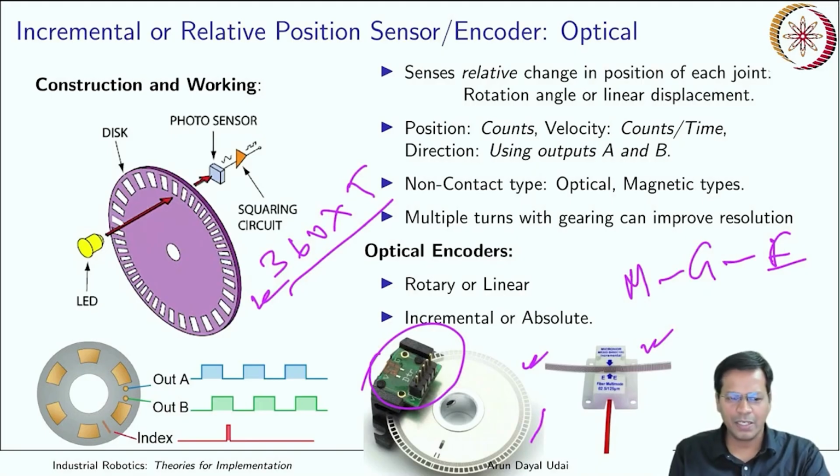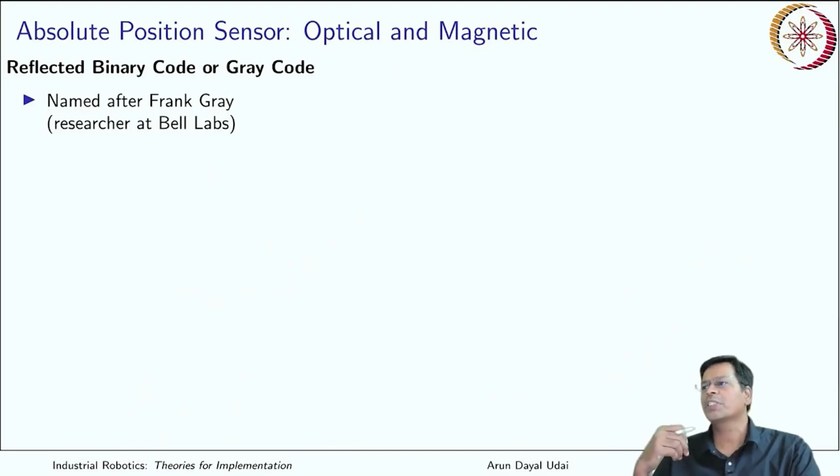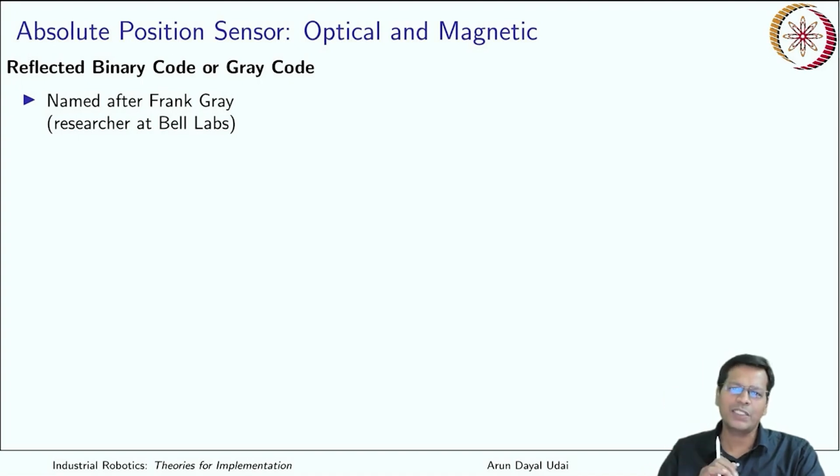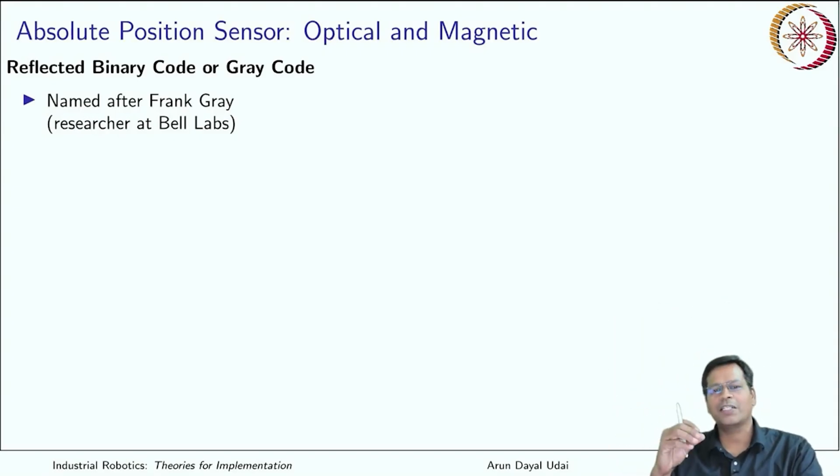Okay, so yes, this is an incremental sensor, and now you see how an absolute position sensor can be made, which can store the value, at least the starting value. So if it moves even when the system is shut down, when it starts, it can directly get where I am. Initially, if you remember your printer, whenever you start your printer, your head goes to the home position. Why? That is probably an incremental encoder. The strip which I showed you is pulled out from such a printer only. So yes, it is an incremental sensor. So your cartridge goes to the home position.